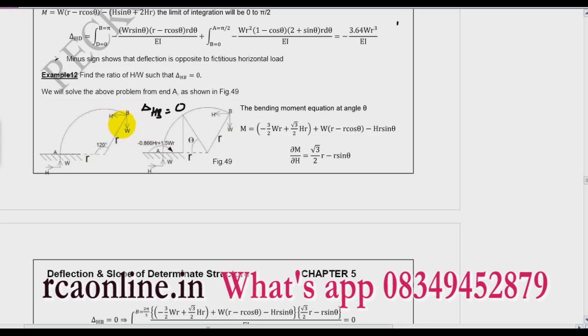Now friends, if you see, the complexity is like this: up to this portion, I draw a horizontal line at C. So if you see, for this portion, this H is giving you the clockwise moment and W is also giving you the clockwise moment. But if you come below C, then what will happen? The H will give you the anti-clockwise moment and W will give you the clockwise moment. So you have to divide this integration in two parts. Rather than doing this, what I can do, you find the total moment at this point.